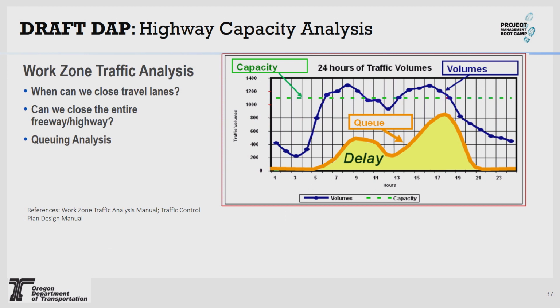When interruption occurs in the flow, the capacity itself decreases because everybody is starting from a stop. At that time, the capacity can reduce to 1,200, 1,300 passenger cars per hour. And if the demand in the consecutive future hours is not less than that, then we may not even be able to clear the queue for entire days, I don't know how many hours, depending upon the traffic.